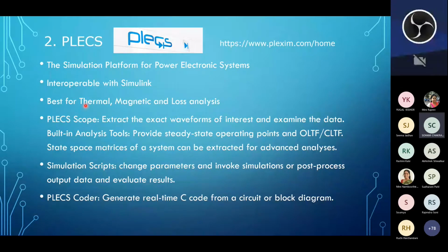As much importance as we give to the control design and maybe to the other design, the same importance you have to give to thermal design. Because I believe 60% of power electronic systems fail due to thermal design problems. Right? You design a converter which operates very fine, results are excellent, maybe efficiency is very good, everything is good, but ultimately you start running it and it will get blown off as soon as you run it for maybe, let's say, 10 minutes, 15 minutes, 1 hour, something like that. Why? Because of these thermal issues. The second cause is magnetic issues, as we are discussing EMI and EMC. So this software is very good for thermal analysis.